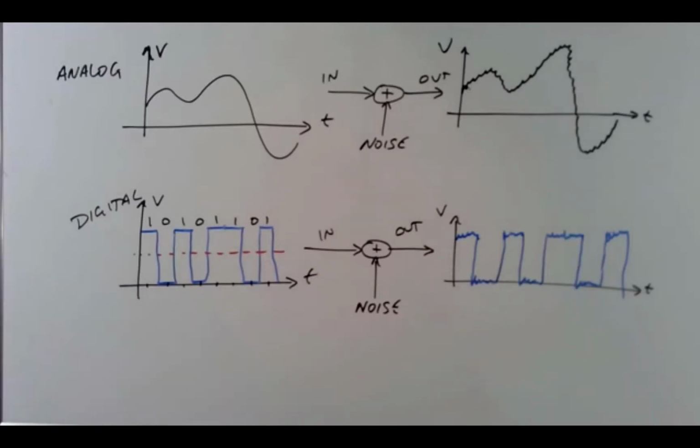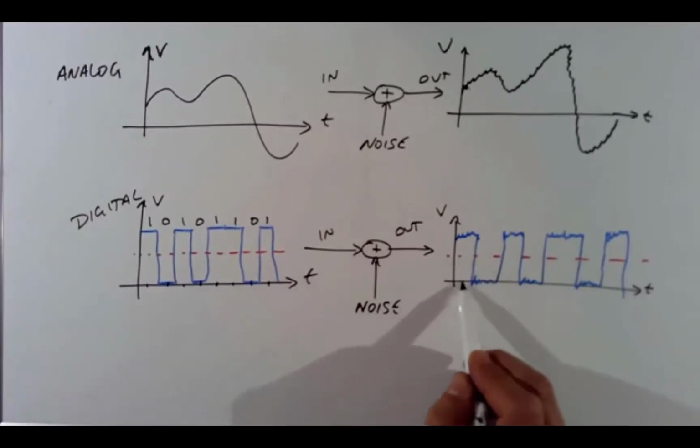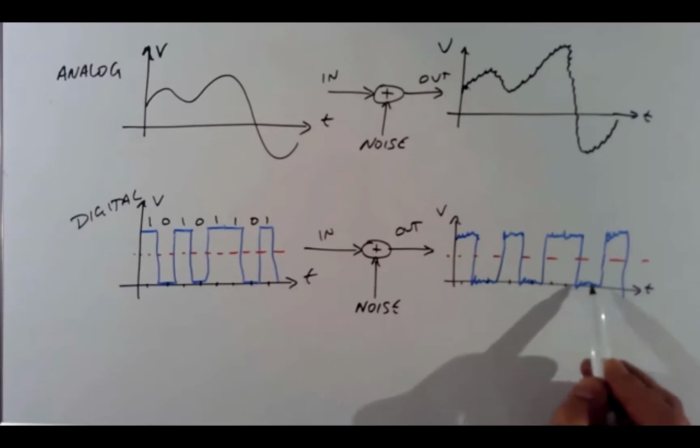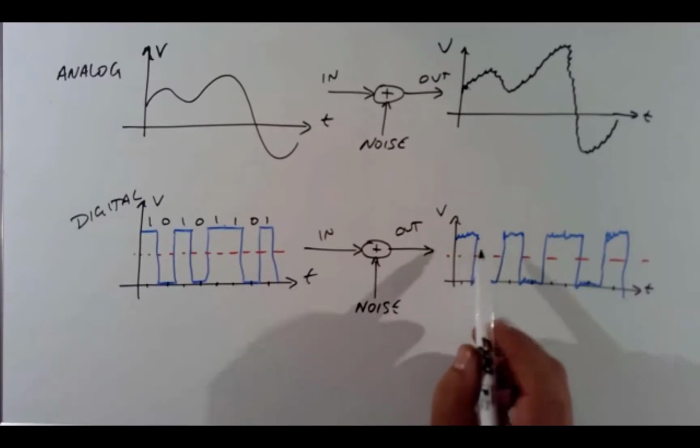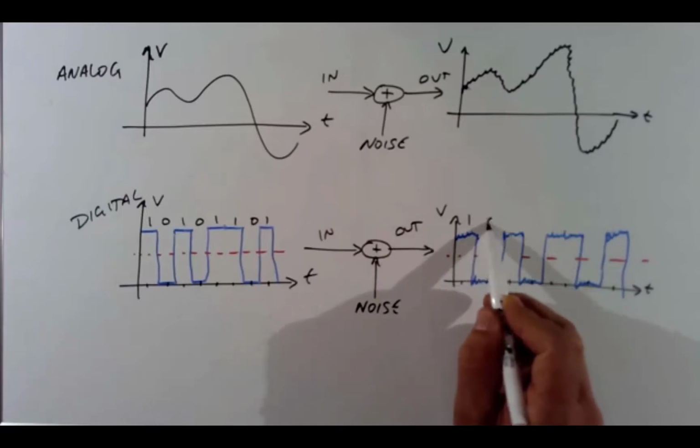And if I establish that threshold, some threshold down the middle, then you can still tell. You can actually still tell, do I have a 1 or a 0 encoded? Any value at these regularly spaced intervals above the threshold, think comparator, is a 1 and any value below is 0.